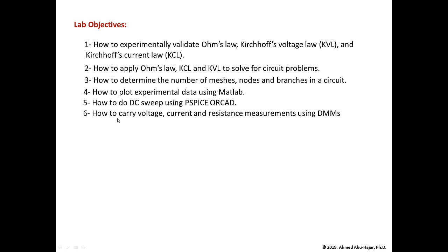Also, you need to be able to measure voltage, current, and resistors using the DMM. This particular skill is carried over from lab 1, but we need to make sure that you know how to measure voltage, current, and resistors. Current usually is cumbersome for students, so pay attention to how you're going to measure currents using the DMM.